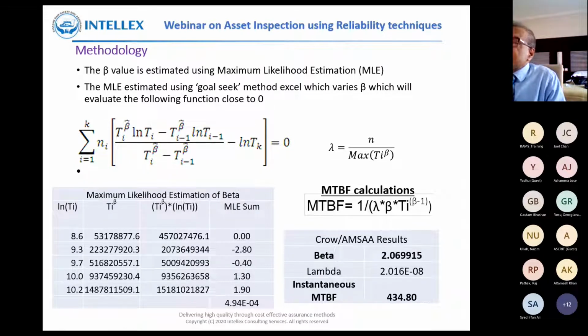So in this, you have 2 parameters: the time interval and the number of failures, and the beta. If there is uncertainty on the beta, you don't know that, but you know the number of intervals, k, and the number of failures also. So this function you need to bring to 0. Whichever value of beta brings this function to 0, that means your parameter is correct. I think you only need to worry about that much when you apply it.